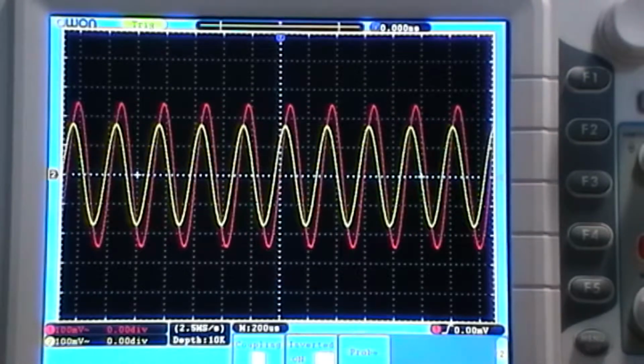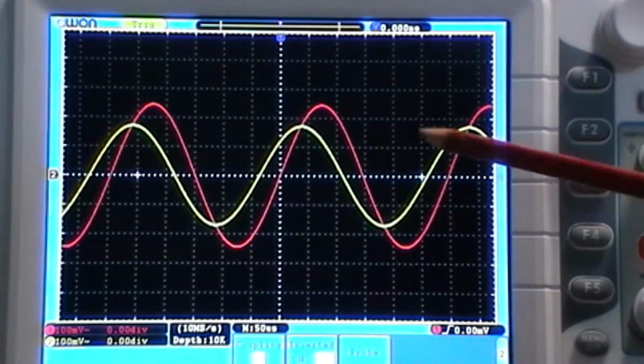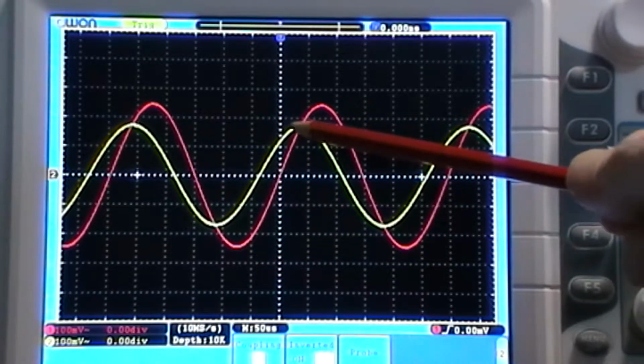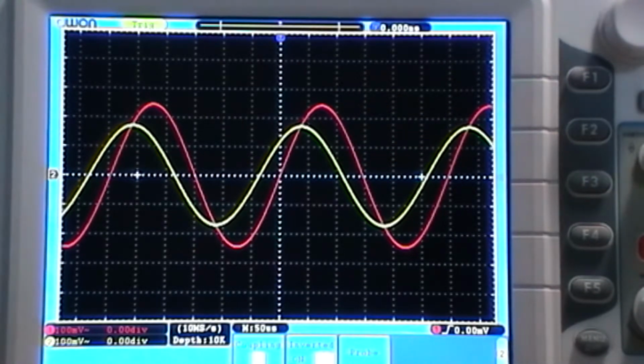Again, turn it that way. When I set the scope like this, you look at it and go, it looks just the same as the other ones, and it should do, because there's my input signal, there's my output, got the phase shift, and it's about -3 dB, as I would expect. Only this time we're at 3.38 kilohertz rather than what the previous cutoff frequencies were.